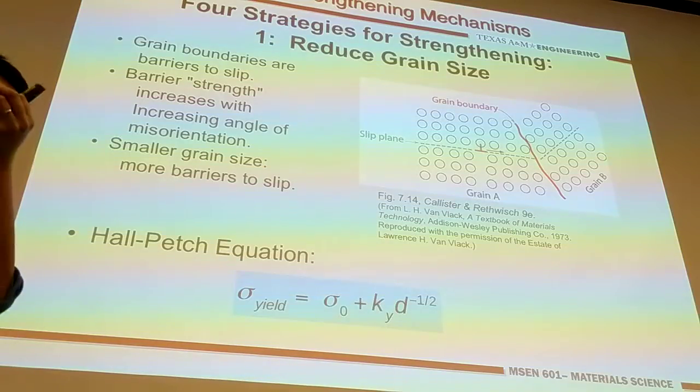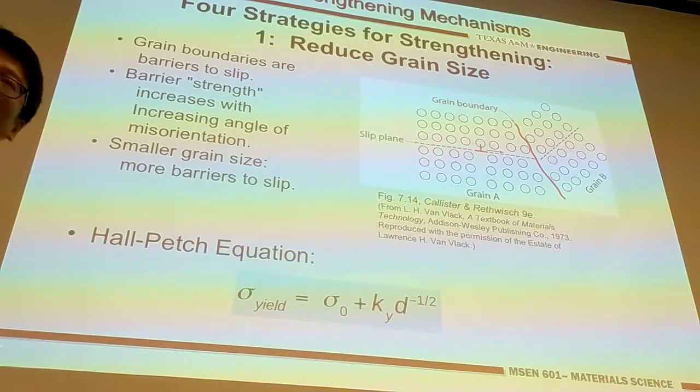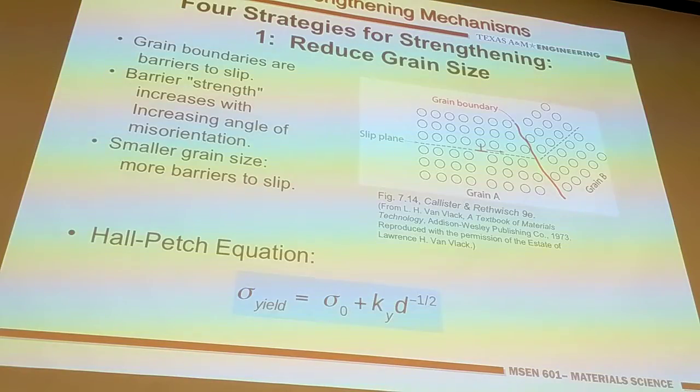If I want to enhance the yield strength, what should I do? I want to delay the dislocation mechanism. I want to delay the plastic deformation induced by the slip of dislocation. So if I can slow down dislocation, then I can eventually enhance the yield strength.